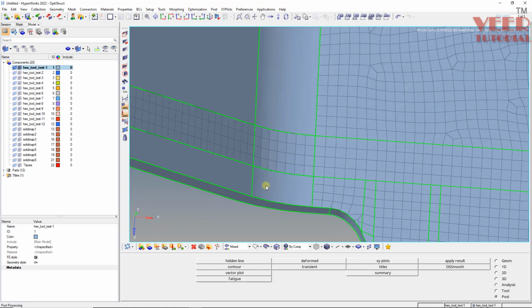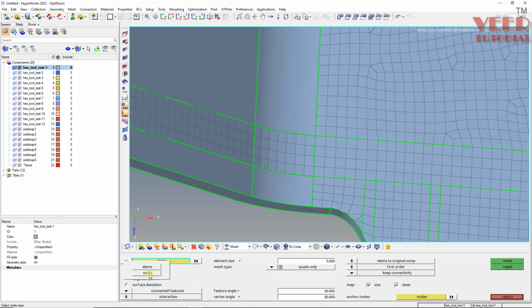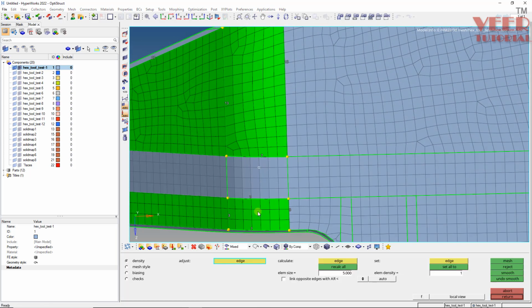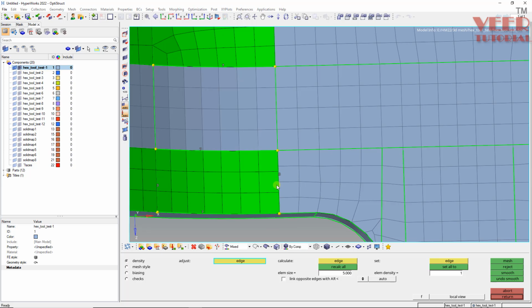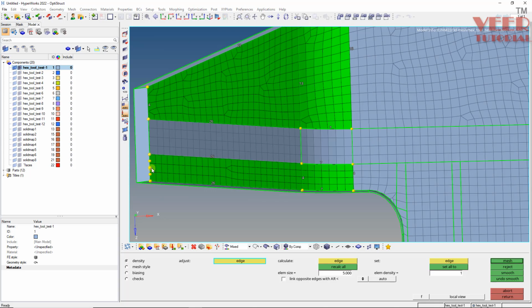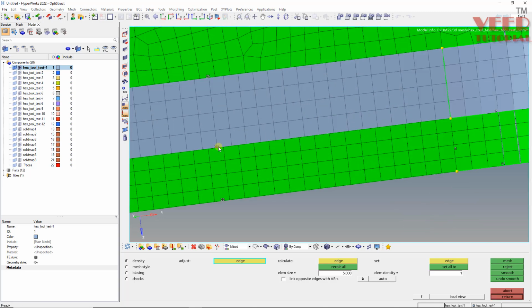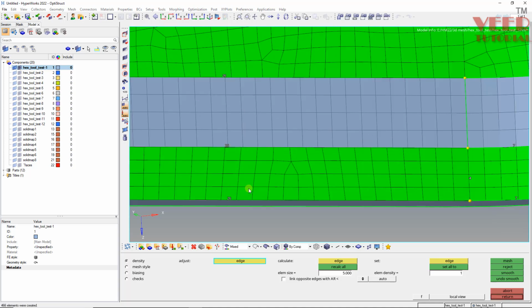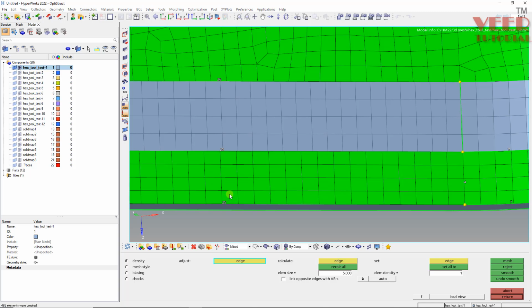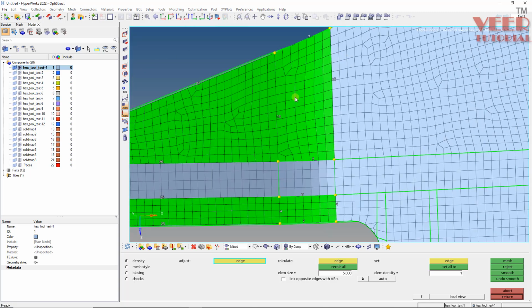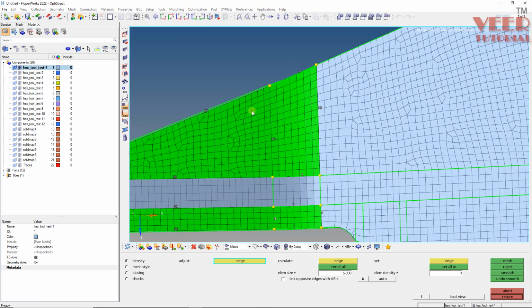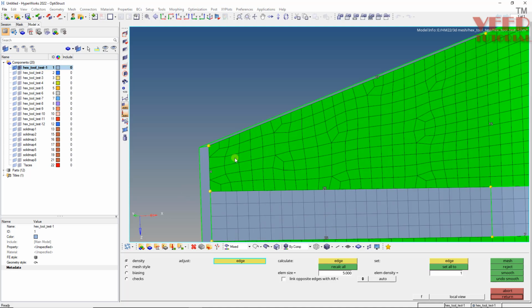And after that we have to do mesh here. So I will select this face, this face, this face, this face. So here 7, we have to make it 4 here. 4 here also, 4 here. And let's say make 25. Okay, we have to make connectivity here. Similarly, here make it 15, and here connectivity is proper. We need to also make connectivity here.